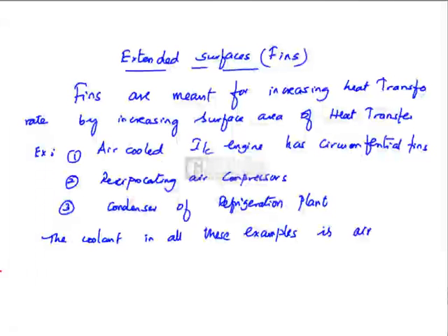Fins are usually preferable or used only when the H values are relatively low. We never find fins when the coolant is water, where the H values are relatively larger or higher.